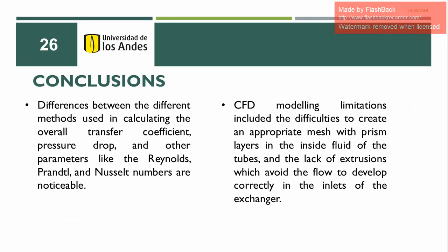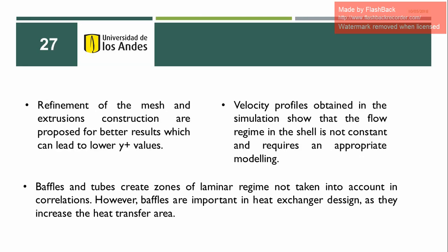Besides this, baffles are important in heat exchanger design, as they increase the heat transfer area, allowing a mix of the fluid and regions of lower velocity which permit better heat transfer. Finally, velocity profiles show that the flow regime in the shell is not constant and requires appropriate modeling. Also, from the temperature profiles, we can conclude that the countercurrent configuration is more efficient in heat exchanger performance.